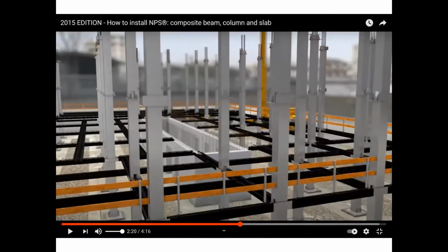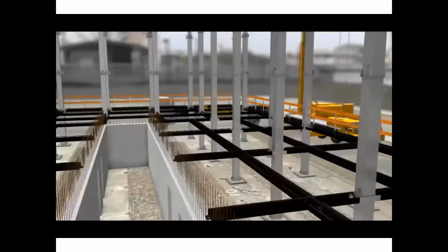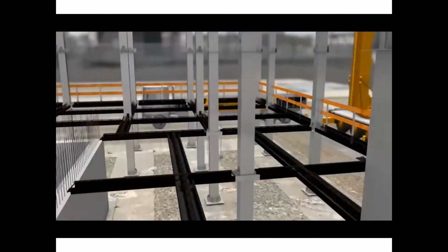The inside part is called core or shear walls. It's a huge amount of concrete. This one is mainly to resist any lateral load. It will be around the elevators, stairs, all of this stuff, just to resist any lateral load, wind load or earthquake. This one is not our topic.